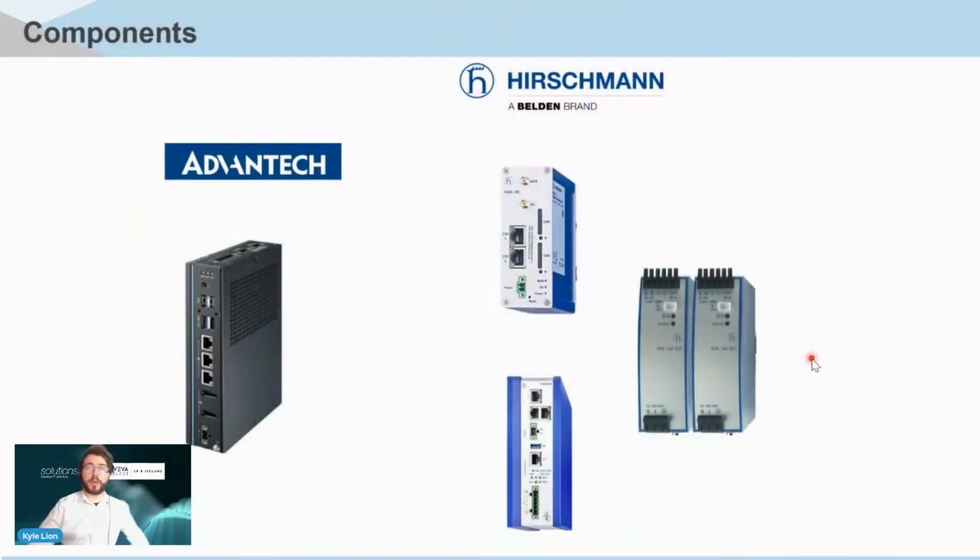These are the components in question, and the main one that we haven't been over here, these are our power supplies. So these are dual redundant PSUs, and in the model that we've actually built, we're using these. And these are SNMP capable. So we can use this to actually bring that SNMP information into Edge. Once we've got it in Edge, we can use that to alert within Insight. So if one of these power supplies goes down at a remote site, we can get an alert automated through Insight to send someone to go and check on it, send a maintenance engineer to go and fix it, without having to necessarily make the trip to site first to see what the problem is.